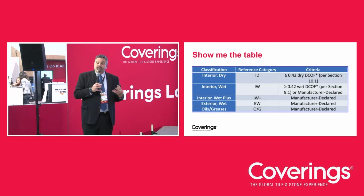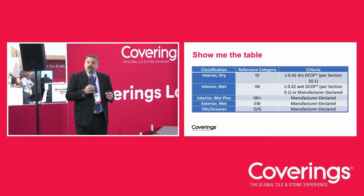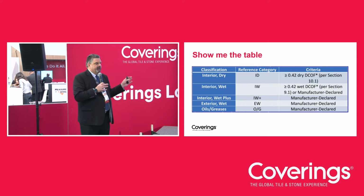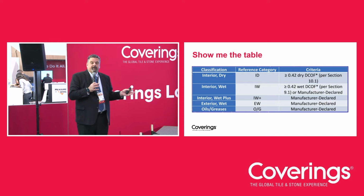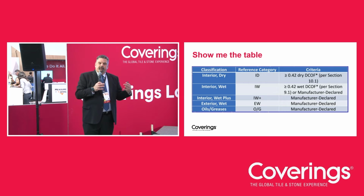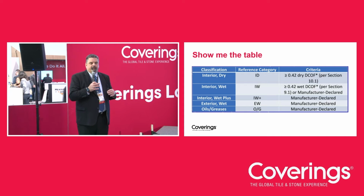The standard at this point doesn't necessarily say a specific number, but if you read through the standard, you'll see there's some suggestions. And it's things like you want a 0.5 if you're going to be in this interior wet plus area, and a 0.55 if you want to be exterior. So there's some numbers in there that start to give you a feel for, okay, 0.42 isn't enough. You actually need a little more COF if you're going to be in some of these more rigorous areas.